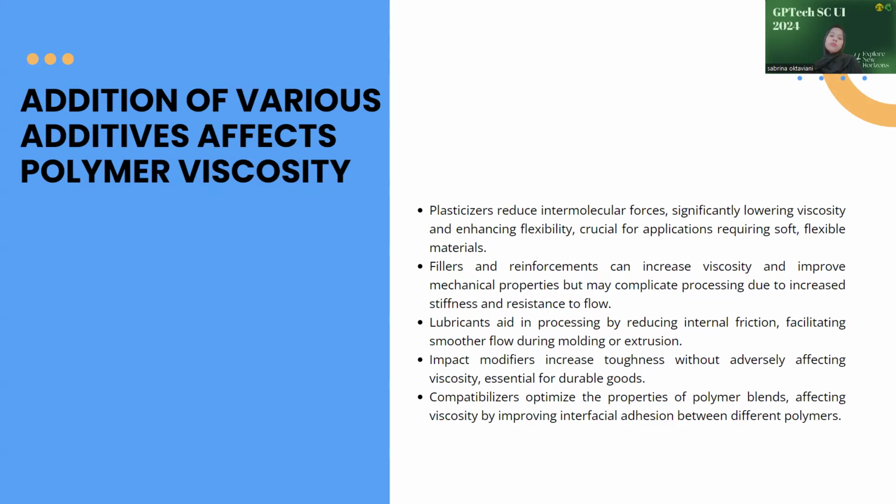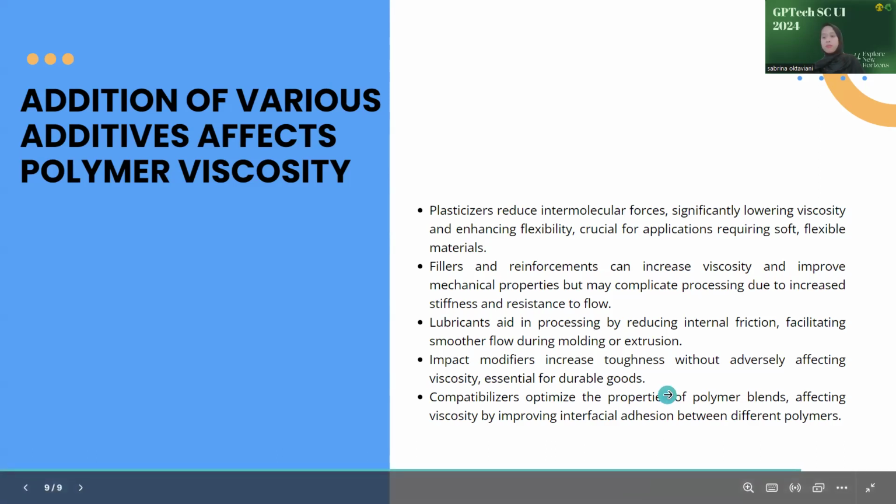Lubricants aid in processing by reducing internal friction, facilitating smoother flow during molding or extrusion. Impact modifiers increase toughness without adversely affecting viscosity and are essential for durable goods. And compatibilizers optimize the properties of polymer blends, affecting viscosity by improving the interfacial adhesion between different polymers.